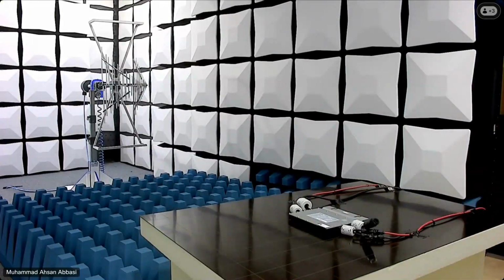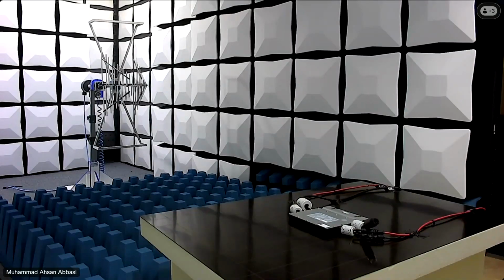But normally, last question, automotive standard. Are you also supporting EMC lab service as per automotive standard CISPR 25? In the Munich lab, for CISPR 25, you need more or less a special setup. Just a moment, I can show you my chamber, and you can see it now. From CISPR 25 setup point of view, your device should have a reference ground plane on your turntable, on your test table, for example, and this reference ground plane with low inductive connections connects to the walls of the chamber, but this is not possible in our chamber.